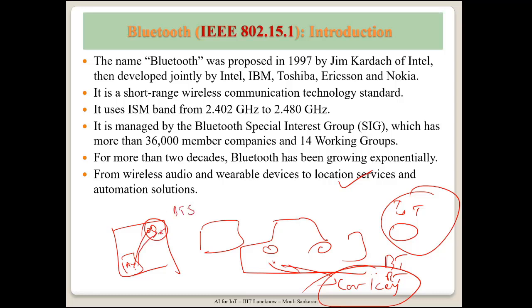So Bluetooth 5.2, which is the latest version, has the location service. It can identify a Bluetooth enabled device, an IoT device in particular, and where exactly it is from your other device. It is like peer communication. It is nothing like an AP. A master is there, but every device can communicate with any other device, peer communication. They pair, and then they can exactly sense the direction as well as the distance between them, so that it can direct you to the place where the key is.